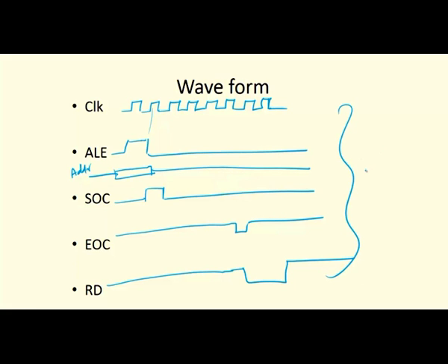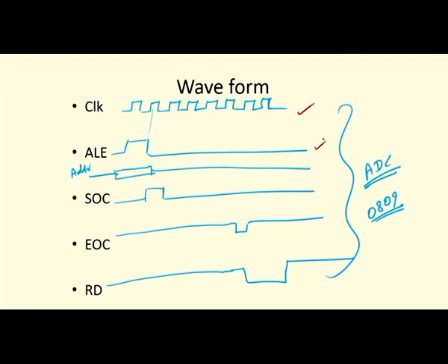These are the wave representations of the analog to digital conversion process in the IC 0809. Okay. So, first we apply the clock signal, then activate the ALE for one period, then we get our required address, then activate the SOC, then we have to wait for this period. Okay. So, after it goes low, now we activate the read, which is an active low signal, that is why during the low period it will read the data. I think you get the idea of the ADC 0809, and we already know the 8051, right.